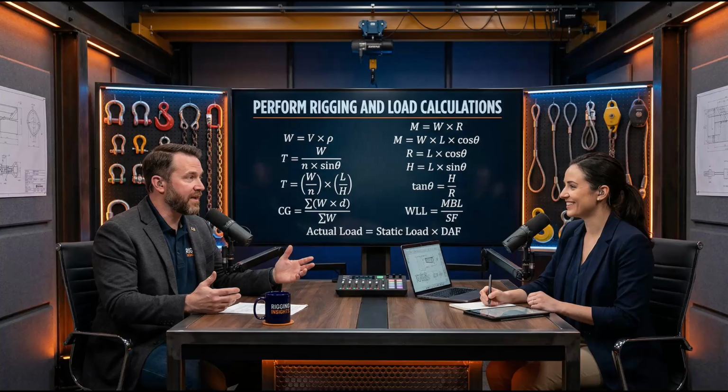But in industrial rigging, you almost never lift with perfectly vertical slings. You can't usually. No, you're usually reaching out from a central hook to the 4 outer corners of a massive box or a shipping container. So for you listening, picture the slings forming a wide Y shape. From the hook, the cables angle outward to connect to the edges of the load. Because they are angled, those cables aren't just pulling straight up against gravity anymore. No, they're pulling against each other. Exactly. They are pulling horizontally against each other. The wider the Y gets, the harder the cables are trying to rip the load in half horizontally, which means they're fighting their own geometry.